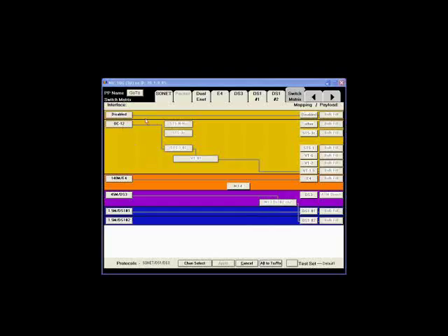I've confused myself somehow. Well, I only have 3 minutes left, but the idea is, if you see there's a line here like E4, it goes straight to its own line interface, so that's an independent test going on. This one is on its own line interface. And somehow without really meaning to, I set up DS3 going through this M13 mux and down to a DS1 number 2. So there are all these simultaneous tests going on.